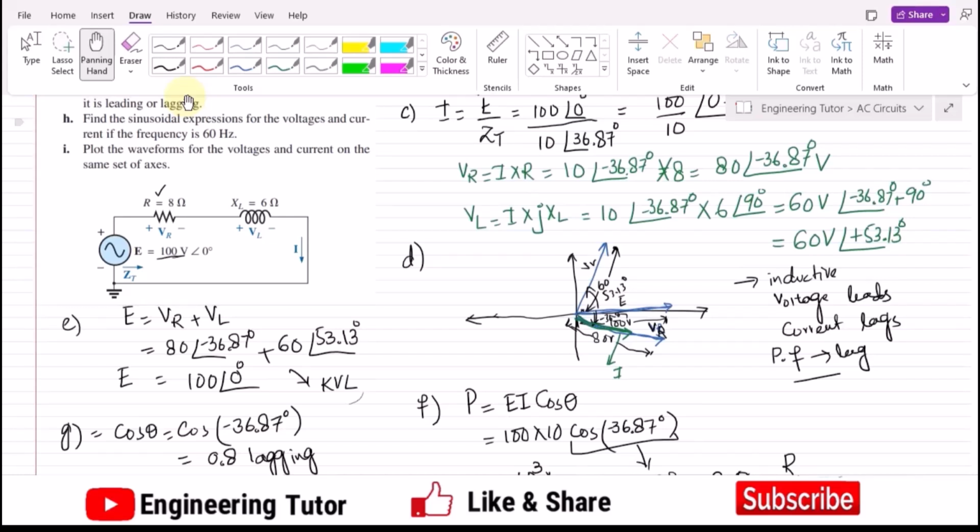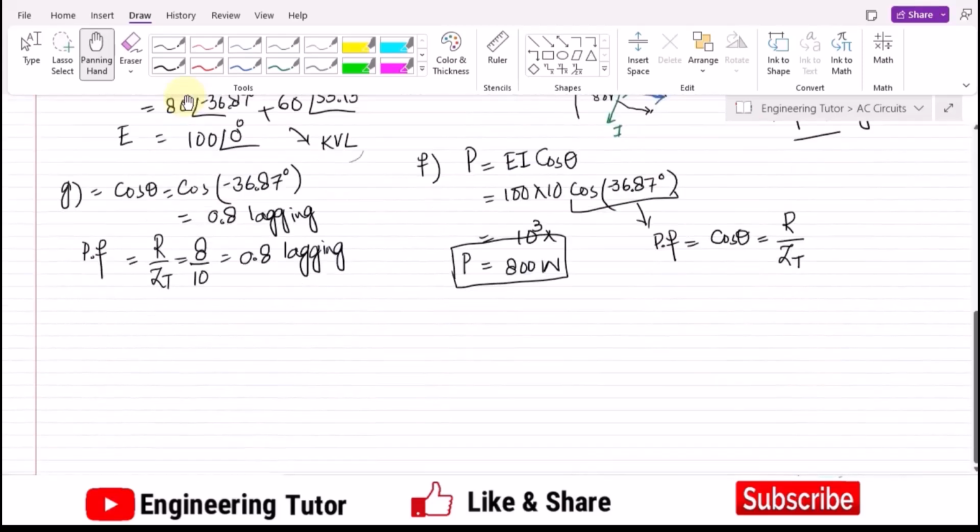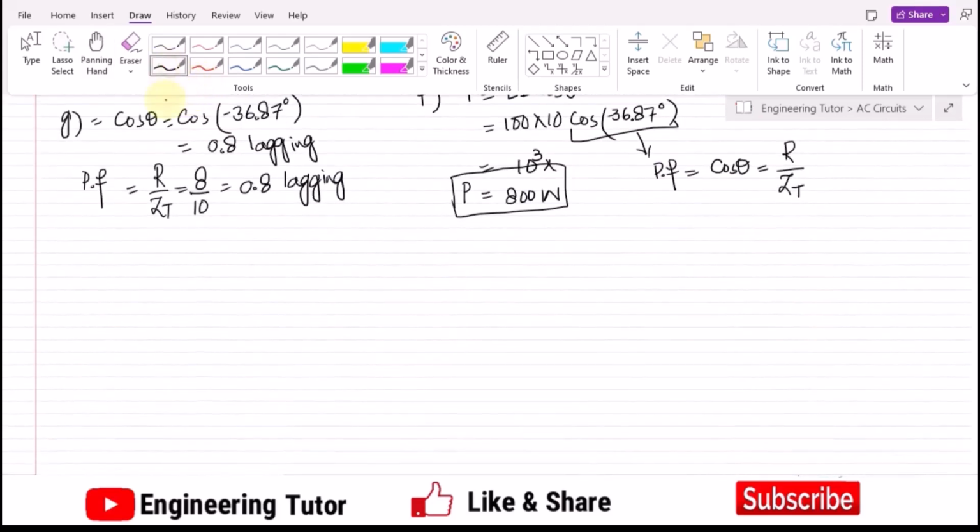So I am going to write the sinusoidal expressions for E, V of R and V of L. Here the frequency is 60 hertz, so the angular frequency will be 2 pi f. Writing their values, 2 pi 60, and that would be 120 pi radian per second.